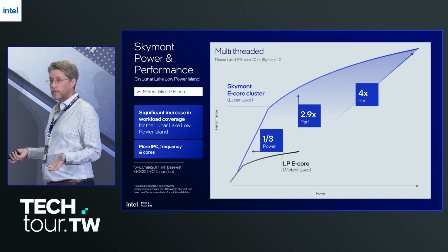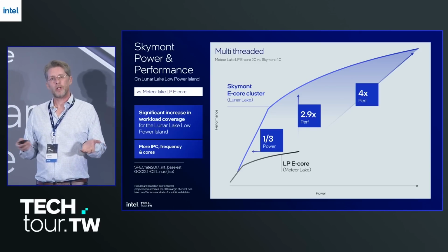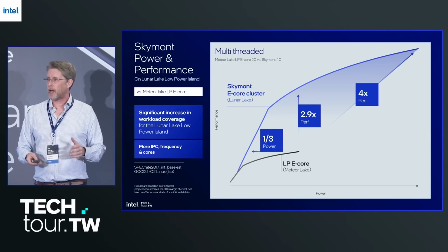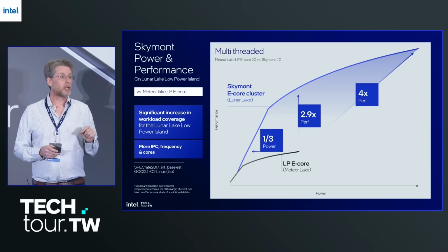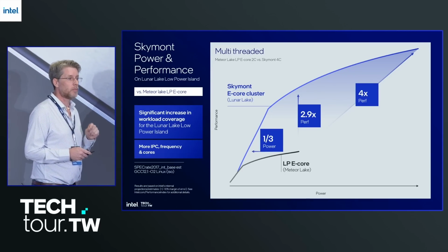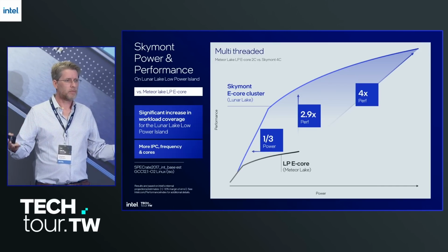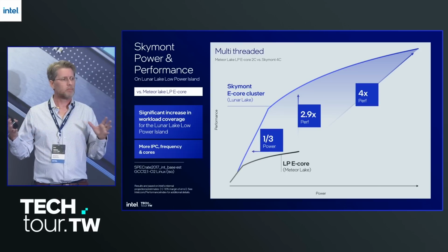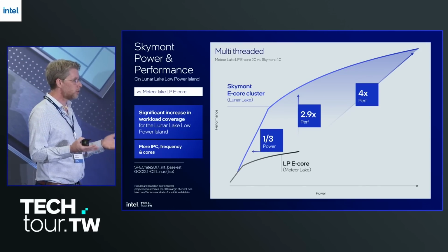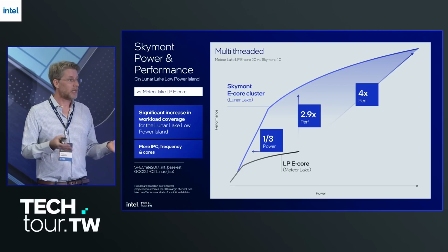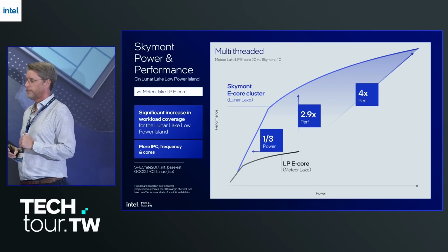So when I talk about coverage, this is exactly what I mean. If you look at Meteor Lake and you do video playback, Netflix, some of these things, something that's very low CPU overhead, we were able to catch that work on those low power E-cores. But if you do something more interesting, Teams, multi-directional video playback, conferencing, it tends to fall off. Those cores don't quite provide enough performance to guarantee the work can stay on those cores. So we fire up a compute tile, et cetera.